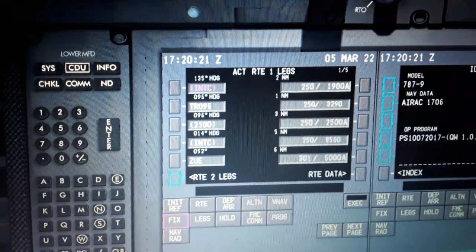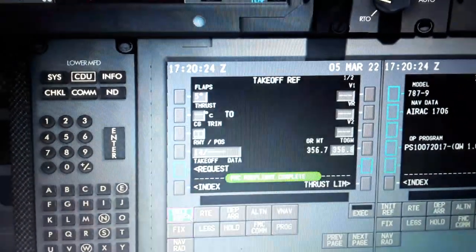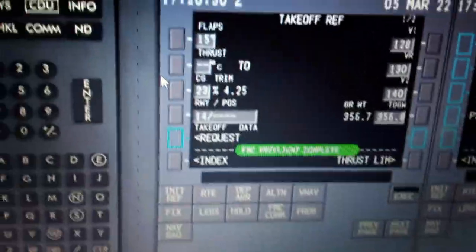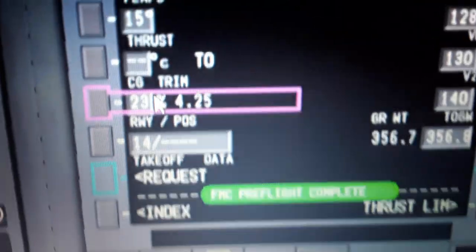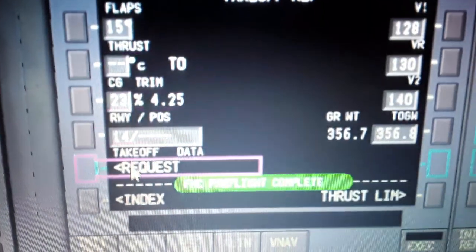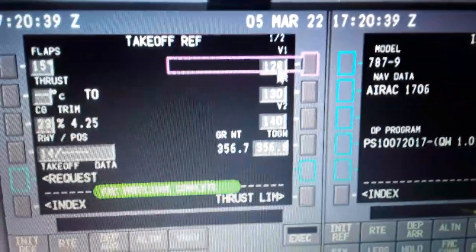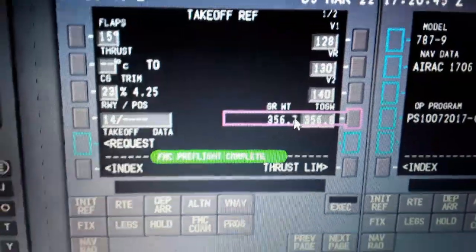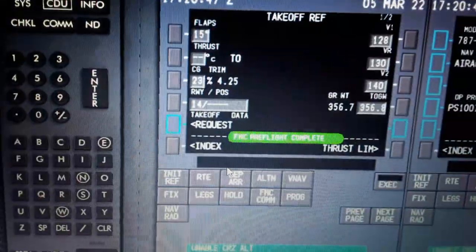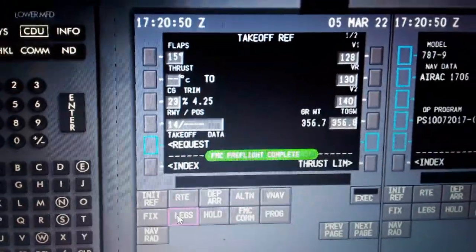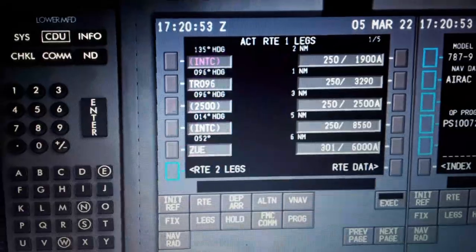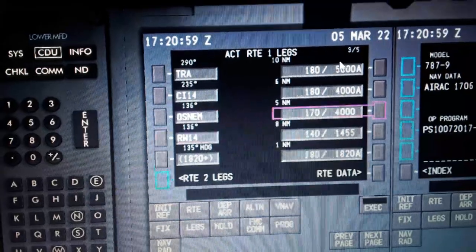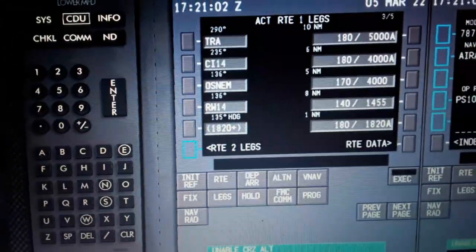We have also the takeoff ground approach. We have initialized here also the flaps for takeoff, 15 degrees, center of gravity over here, trim. You can use center of gravity trim, flaps 15 degrees, runway request over here, V1, V rotate. So these are the takeoff speeds, V1, V rotate and V2 for this takeoff gross weight over here. So we see the legs one by one over here, route legs, and airspeed and altitude constraints, approach, landing over here. So the flight plan is complete.